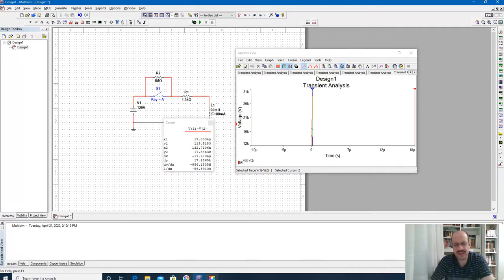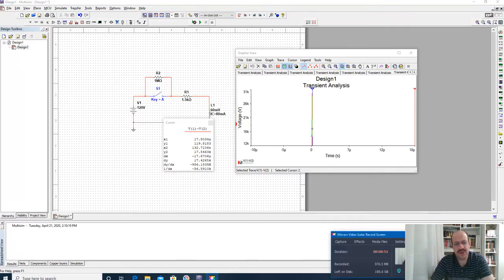That's pretty much the one for transient analysis, and you should be able to easily use it for any circuit. For the normal circuit, use zero initial condition. But if you have to simulate a circuit like the one I showed here, where you have an initial current in an inductor or initial voltage in a capacitor, use initial condition for your simulation and also use initial condition for the component in the circuit.